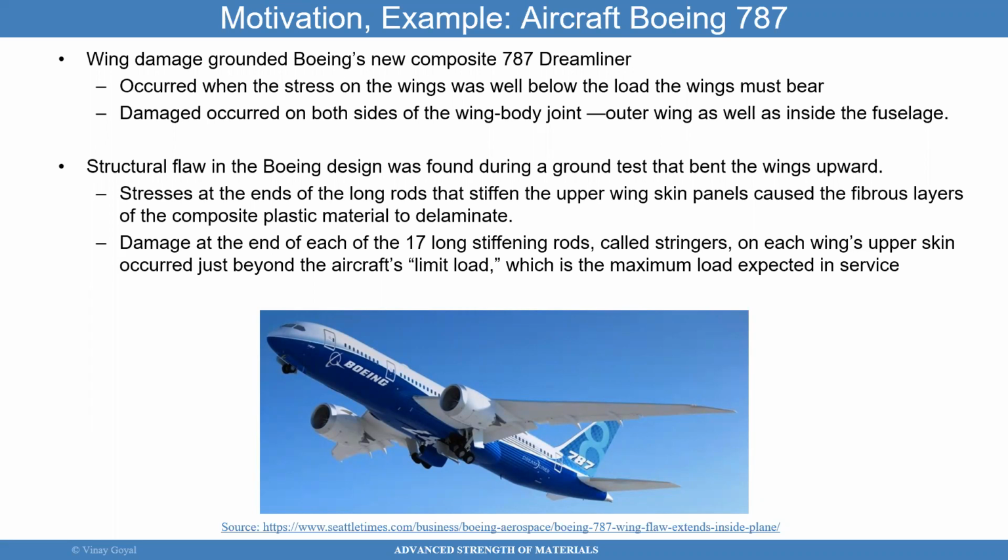Number one. Number two, the testing is done on the ground. You do the testing at ultimate conditions on the ground by bending these wings as much as you can. But to be able to formulate a successful test program, you have to be able to analyze the flight conditions, because in flight, the stresses induced in the aircraft are different than on the ground. And what you want to make sure is that the stresses during flight conditions are enveloped by tests on the ground the best you can do it.